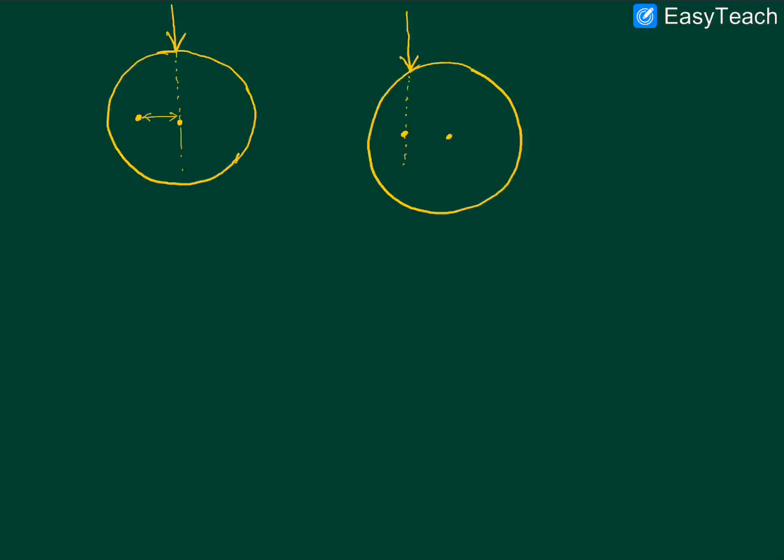Now you note that we have been having this discussion as regards to transverse forces. It is also possible that we can have forces which are not transverse, rather parallel to the longitudinal axis of the beam, in which case it is very much possible to have not only bending moment but also twisting, but in addition to those two, also axial forces.